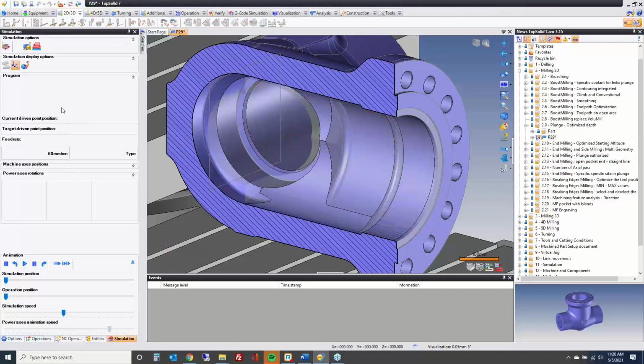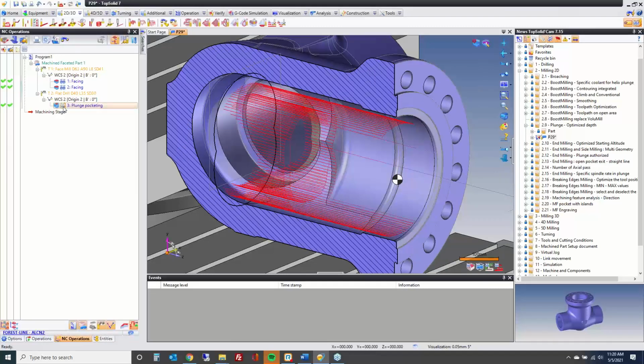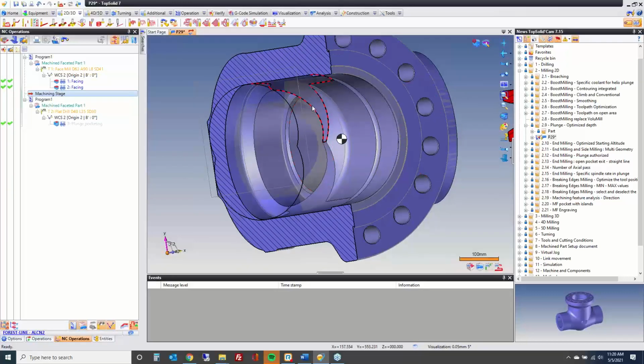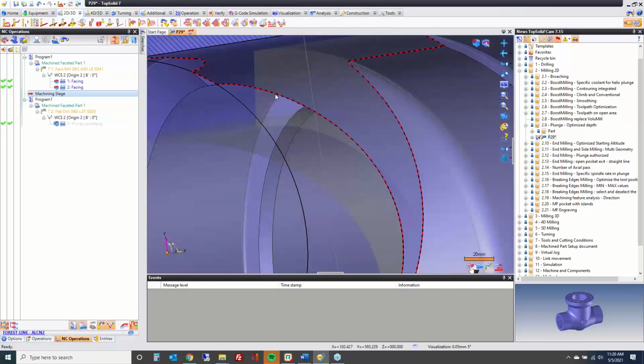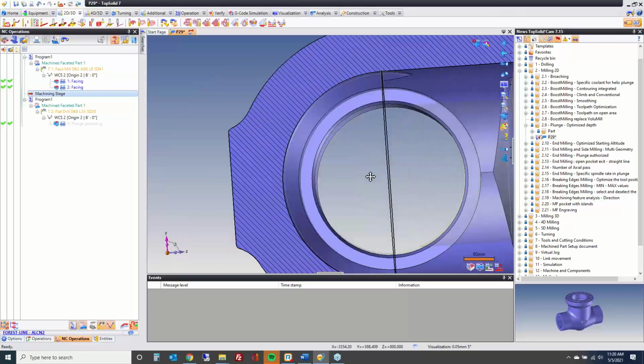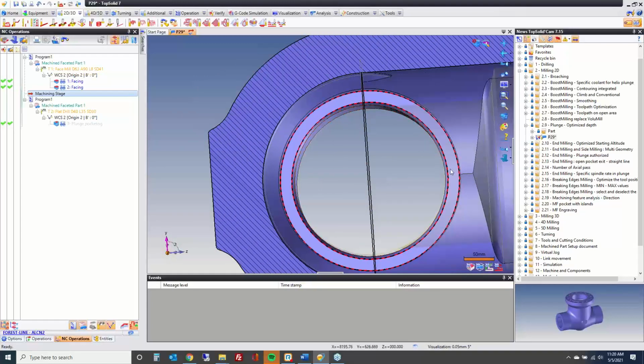Let's turn this off for the moment. Sorry. So I'm going to roll this back so you can see the stock. The center was drilled out with a big drill already, so there's some material here, right? And this cross hole has been drilled already. So being that the cross hole is drilled, there isn't as much material here at the peak relative to the tool axis as there is over here.